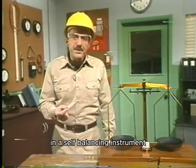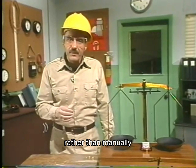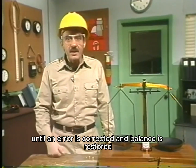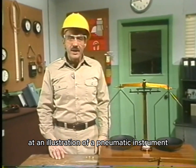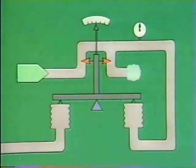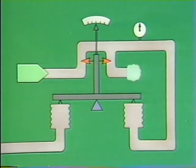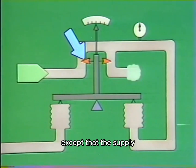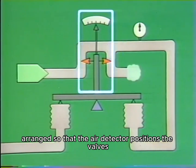Now, you'll remember that I said pneumatic instruments are self-balancing. In a self-balancing instrument, the output is changed automatically rather than manually until an error is corrected and balance is restored. So let's look at an illustration of a pneumatic instrument that is self-balancing. It balances itself. Now, this illustration is similar to the previous example, except that the supply and exhaust valves in the balancing mechanism are arranged so that the error detector positions the valves.